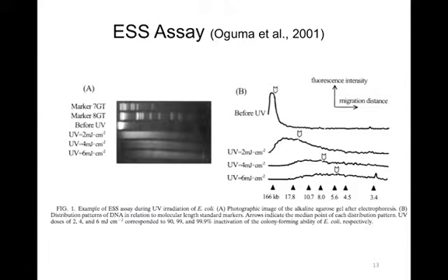I also just wanted to make a point about the doses. She found that a dose of 2 millijoules per centimeter squared resulted in 90% inactivation when she measured inactivation using a common culture-based method. What I reported earlier in the semester was, I think, a dose of 3 or 3.4 millijoules per centimeter squared.